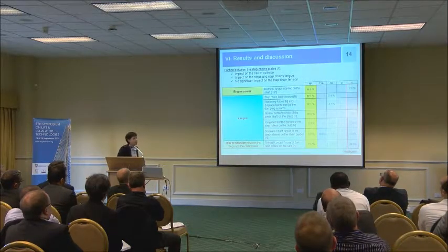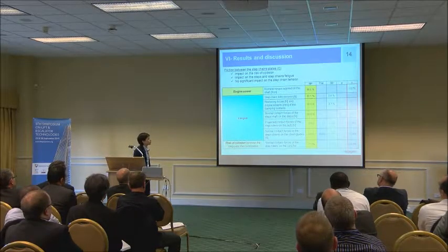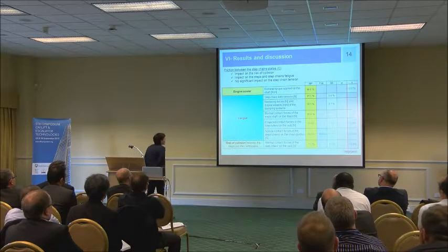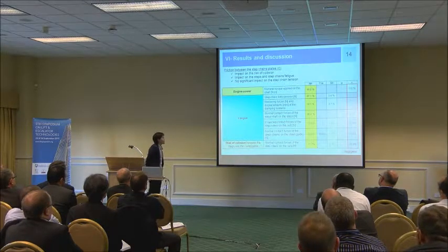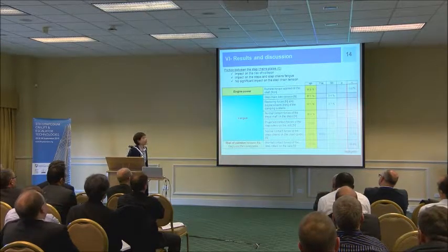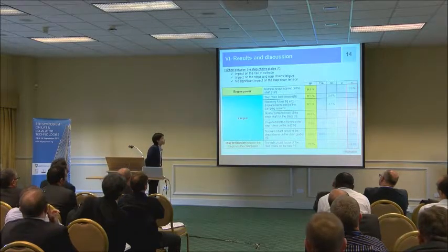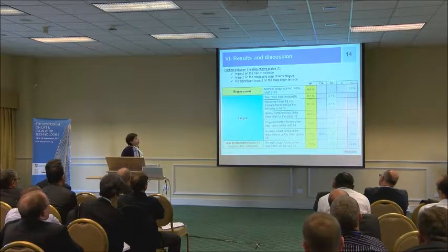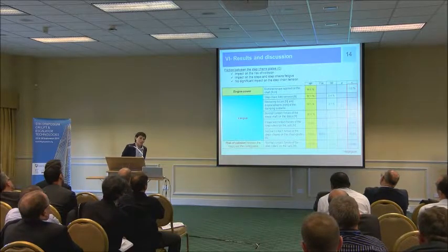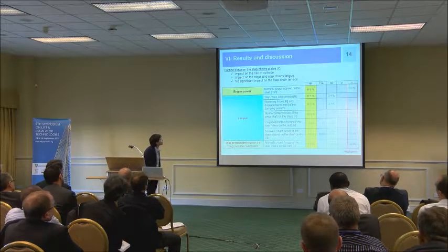The second parameter is the friction, the step chain lubrication efficiency. It impacts both the risk of collision between the steps and the comb plate and the step band component fatigue, mostly the steps and the step chain. A result that we weren't expecting is that poor lubrication doesn't impact the step chain link tension.